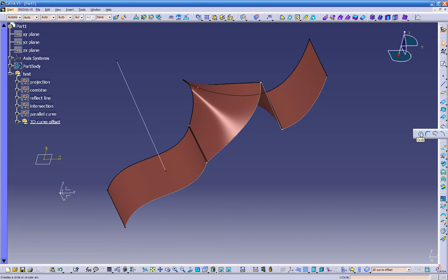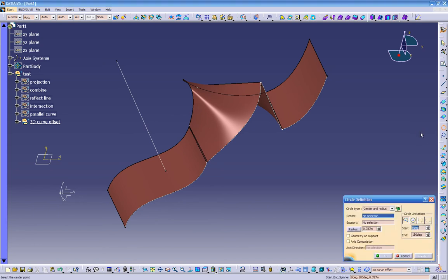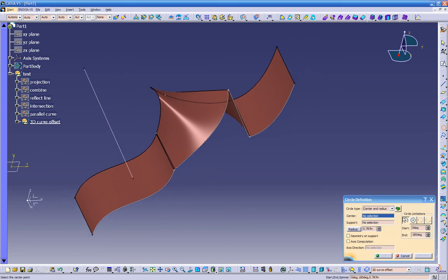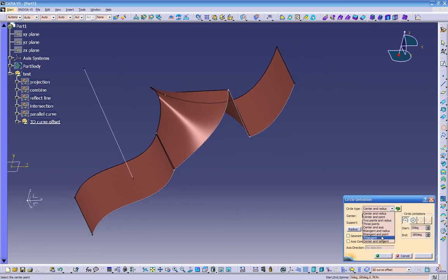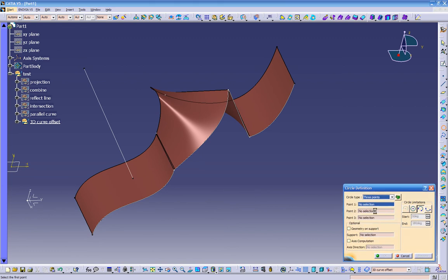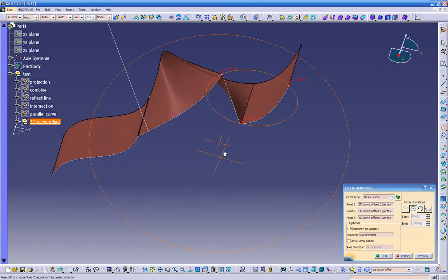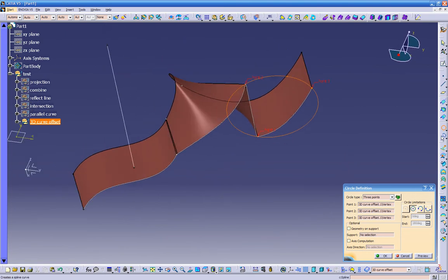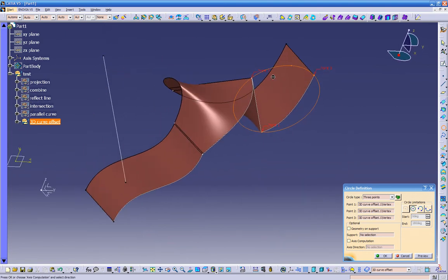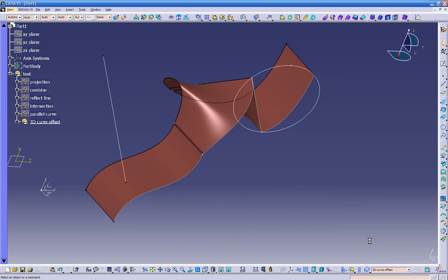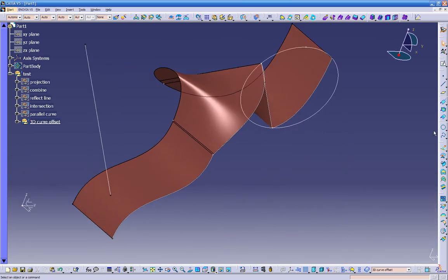You just click on a circle, and then you see over here you have a couple options you can choose from, 3 points, and just click on it and then just grab your arc. So this is pretty self-explanatory. Everything that we're talking about over here is 3D, so there is no sketch. So you're building this arc in 3D mode.